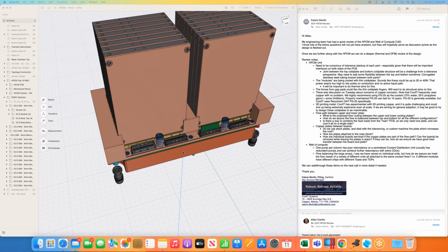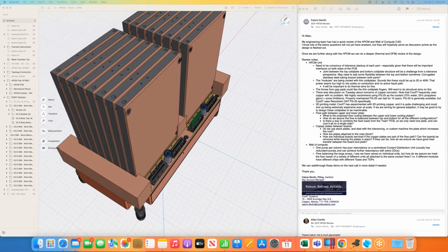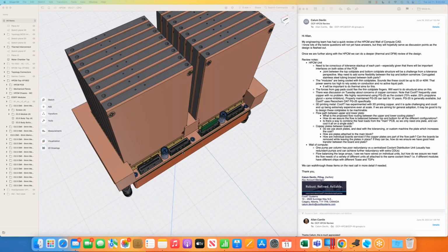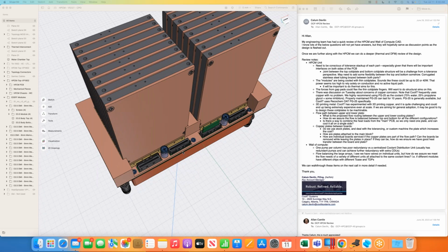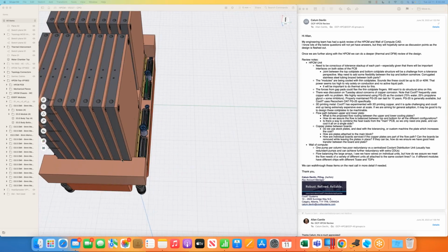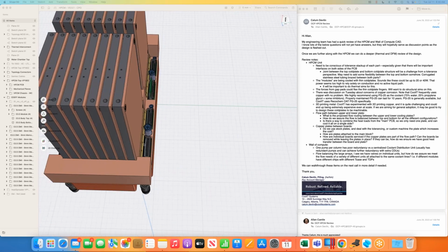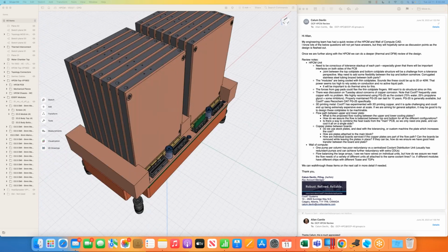Okay, so in terms of tolerance stack-ups elsewhere, Callum, the only other areas that I'm thinking of is, I guess, the spacing between these modules and their mating with these connector type fingers for the thermal conduction as opposed to electrical conduction.